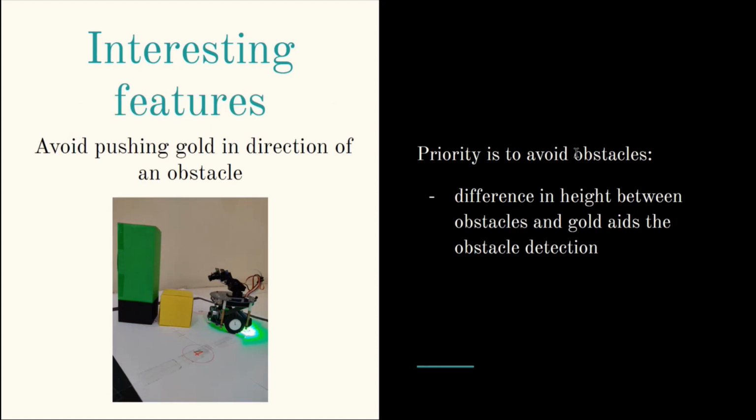Another interesting feature is avoid pushing the goal in the direction of an obstacle. Here I'm using the difference in height to aid the camera to see the obstacle behind the goal. If there is an obstacle detected behind the goal, it will just turn away instead of pushing the goal.